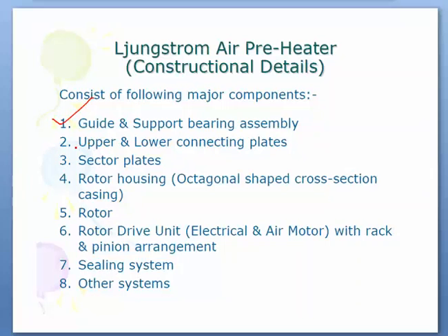Then come the upper and lower connecting plates, details of which we will see in coming slides. Then the sector plates, which make the partition for the flue gas path and the primary air and secondary air path. Then the rotor housing, a total rotating system where it is housed, and that is basically octagonal in shape.